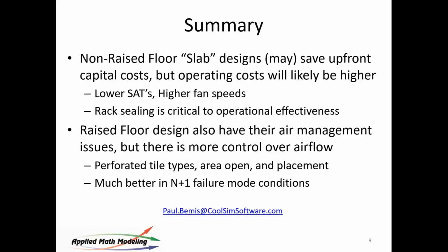Raised floor designs must be chosen more carefully. Modern day servers are now much heavier. Yeah, that's true. So you have static loads, static pressures, a bit more intense. Yeah, perforation of the tiles, you are right. They have to be strong enough to be able to handle the load. That's true. So you need to worry about weight and static load and just heavy load for sure.